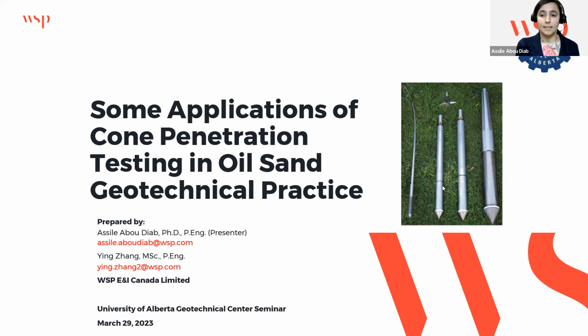This data is transmitted directly to a computer on site. Then the raw CPT data is interpreted using a bunch of empirical correlations in order to evaluate the soil behavior and estimate some geotechnical parameters that are of use and interest to our design.